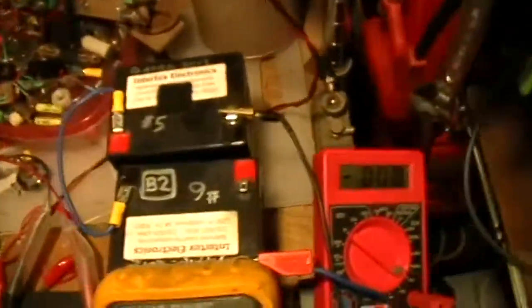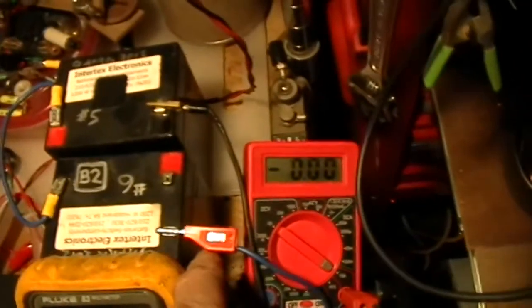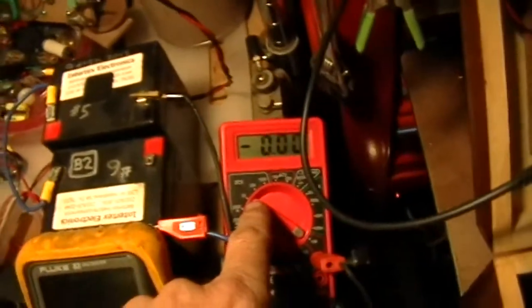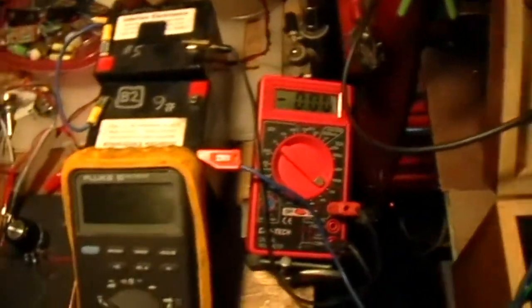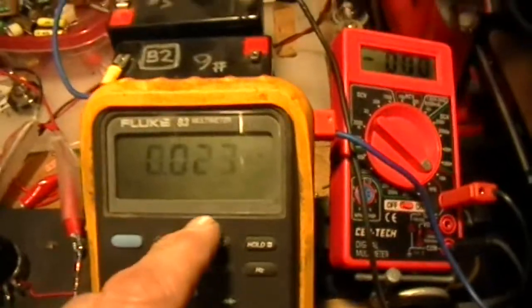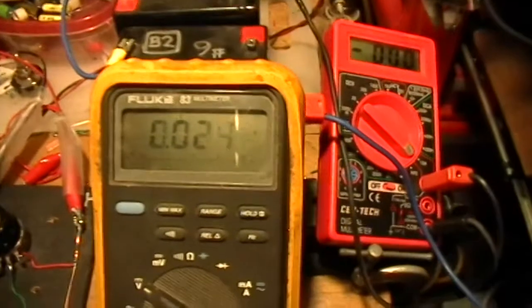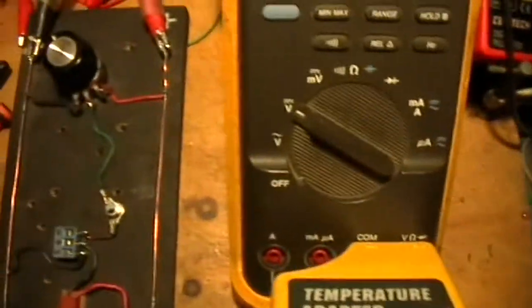And over here I've got the 2 batteries. We're just running with 24 volts right now, and I've got that disconnected. This is an inline current meter just to tell me when I'm drawing current. Here I have the Fluke 83 multimeter with its temperature adapter monitoring a thermocouple that is attached to the Q1 MOSFET. So we're monitoring the temperature of the Q1 MOSFET, and that's in degrees centigrade right there. So we're looking at 23 degrees centigrade on that MOSFET right now.